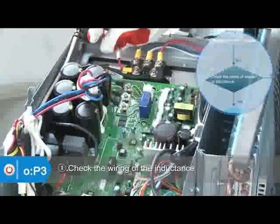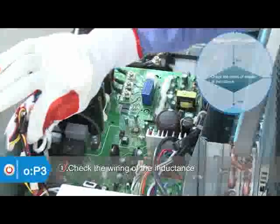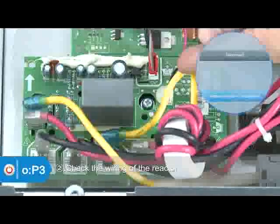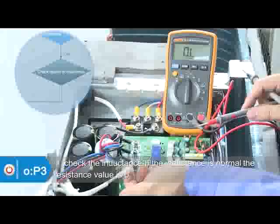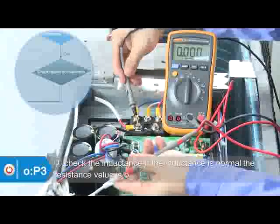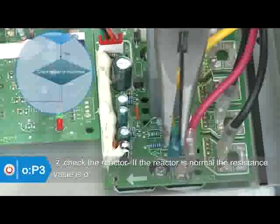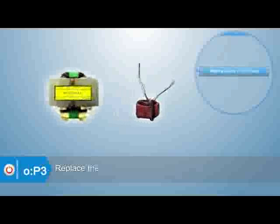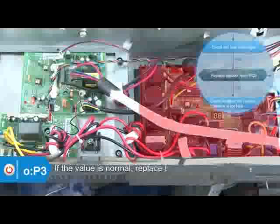If the error still exists, check the wiring of the reactor or inductance. If the wiring is correct, measure the resistance value of the reactor or inductance. If the reactor or inductance is normal, the value is 0. If the value is abnormal, replace the reactor or inductance. If the value is normal, replace the outdoor main PCB.